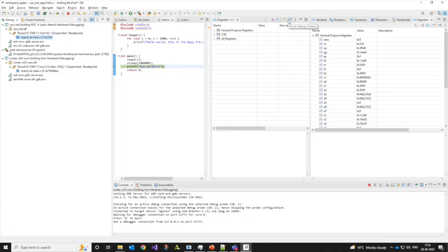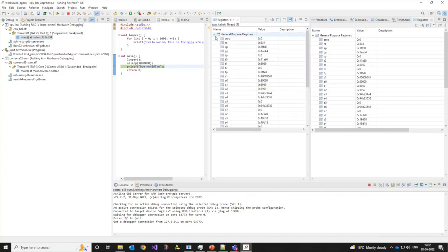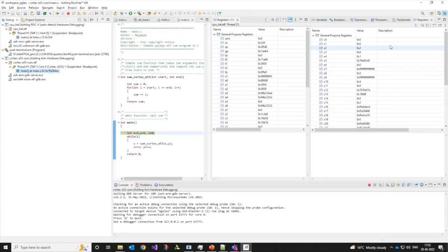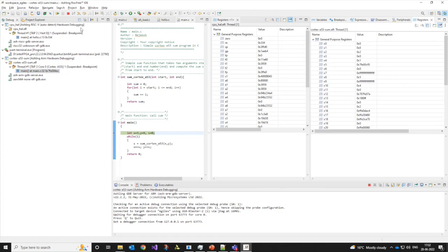I have the pin option here. Once I do the pin option, you can see the red, green pin being shown here. So this view is now always going to show the Nios V registers, and I'm going to pin the other register view against the ARM. So on the right, we're always seeing the ARM register views. And now we can do all kinds of debugging.